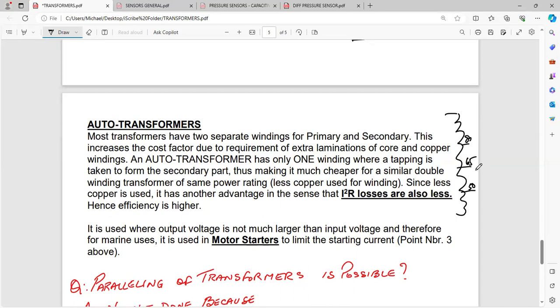And in your auto transformer, it is going to be the step down. So that means your primary is going to have all the total number of windings, and your secondary is going to have for 50% this much, 65% this much, and 80% this much of winding. So it's going to be a step down transformer. So we know that in this auto transformer, we are going to reduce your current to even lesser than your star delta motor start. Also, the voltage is reduced substantially. So that is why you can use these auto transformers for your motor starter. But